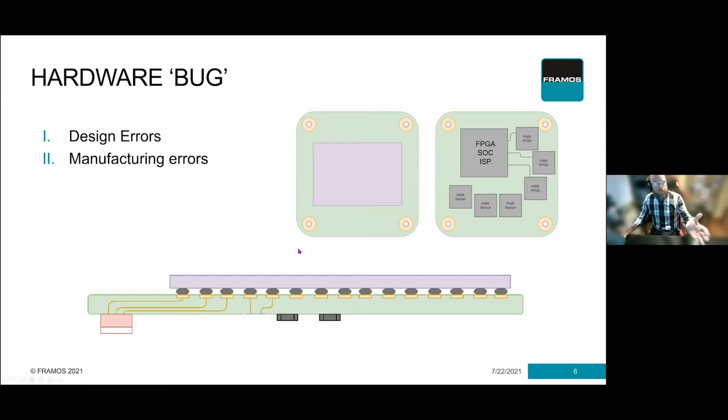And then we have manufacturing errors. So again, these are physical issues. Typically, there are things like additional solder, so shorts are what we typically deal with, where during the manufacturing process, we've broken the concept that was in the design. So if the design's perfectly fine, but the CM uses the wrong process when backfilling vias or creating something within the PCB mask, then you will have an issue that you have to debug, because everything checks out in a schematic, everything checks out across the whole paperwork side of things. It's just physically we now have a bug that we have to track down.